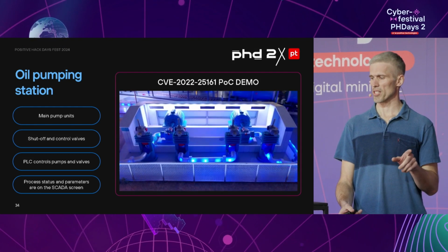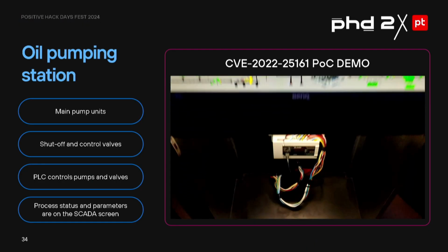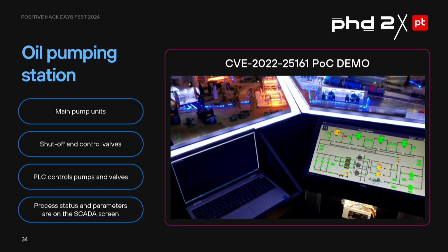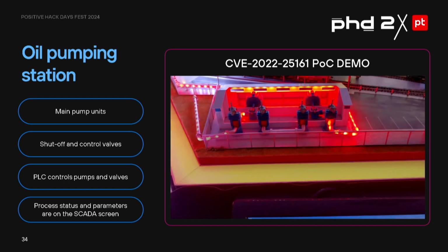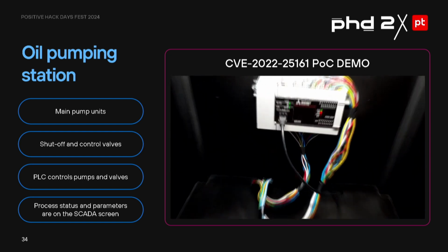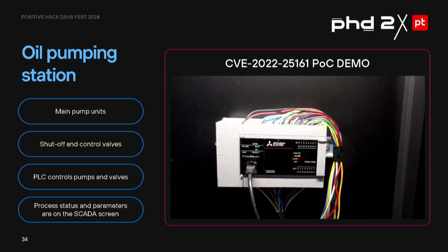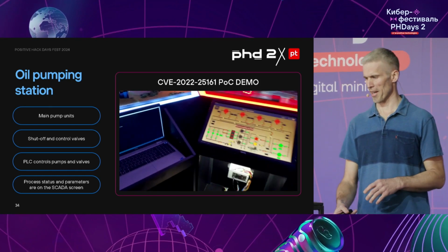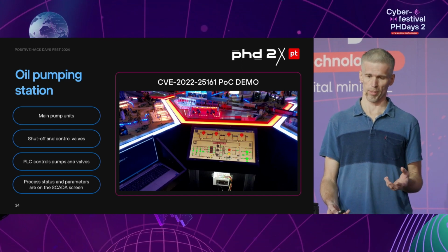You can see here, this is a denial of service. Now, this is the SCADA. This is the Mitsubishi FX5U. It is blinking at us, winking. Now we start the process. Everything stops. SCADA is horrified, and this is the PLC in a mode that you can take it out of only by switching it off completely and restarting it again. It's completely dead for the automation system.